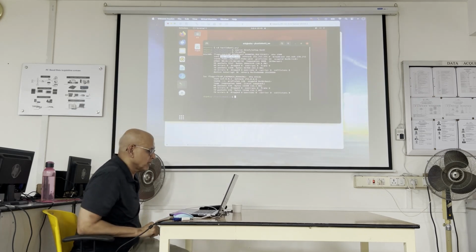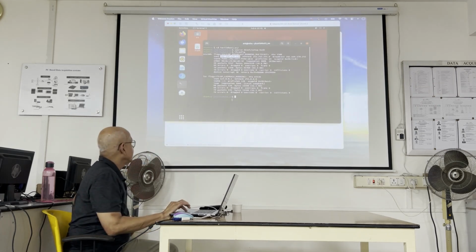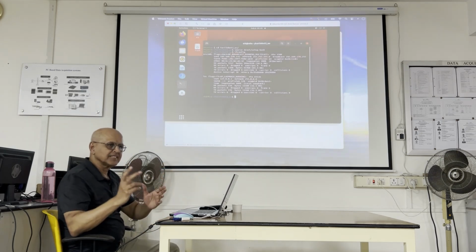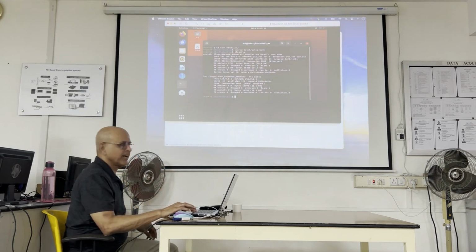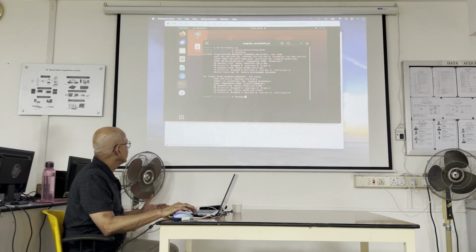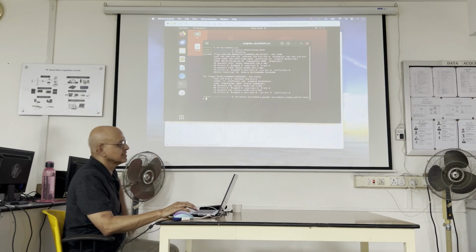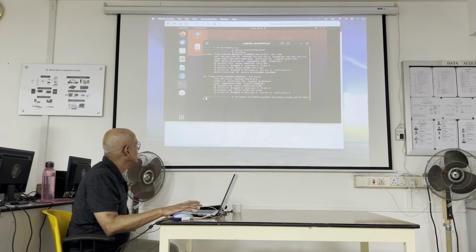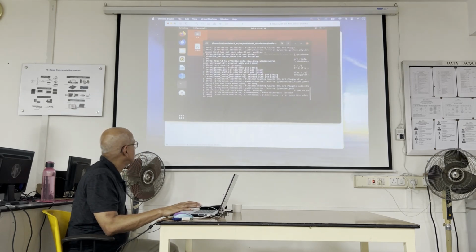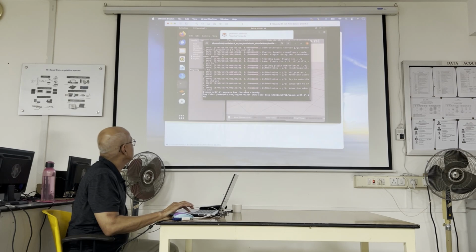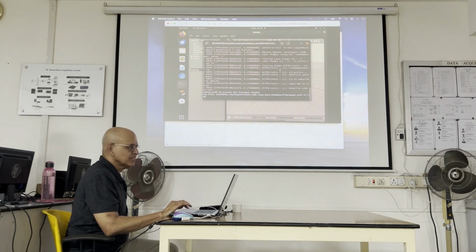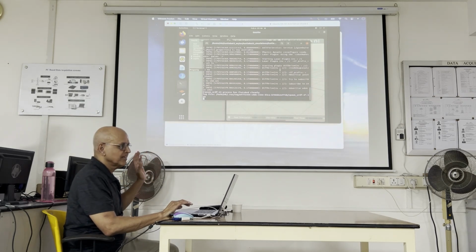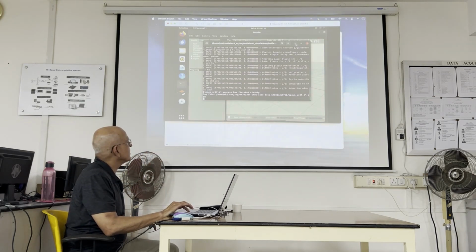Now we're going to launch the Gazebo simulator, and you can tab complete your way to finding the right launch file. It's the empty world launch, but I believe I was working with it earlier today. Hopefully, yeah, there it is. So you can cycle up, find it, and run it. So we don't need this window. Don't close this window. Don't Control-C out of it, because this process has to be live so long as you want Gazebo. So just minimize it.